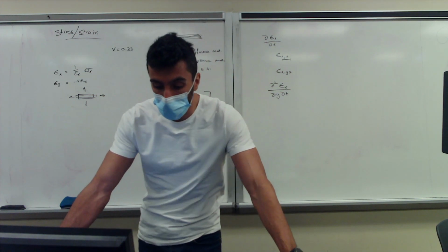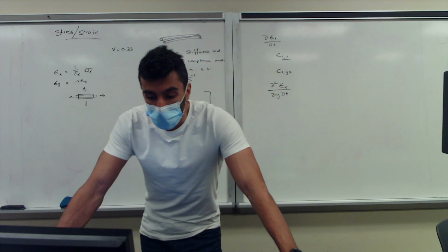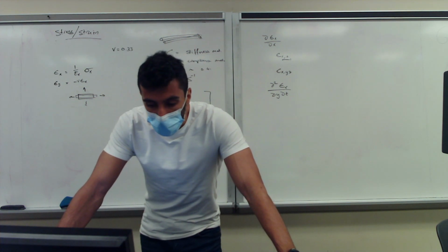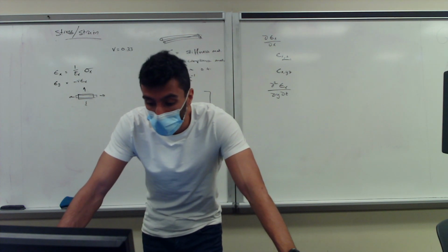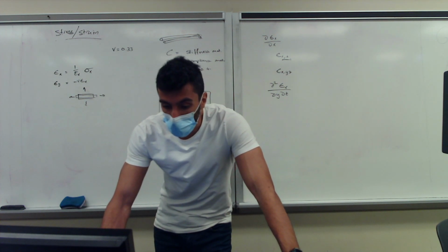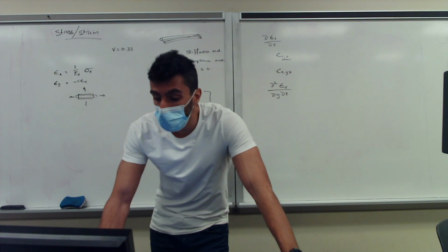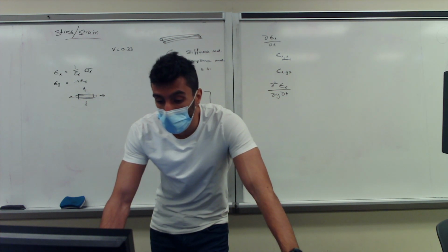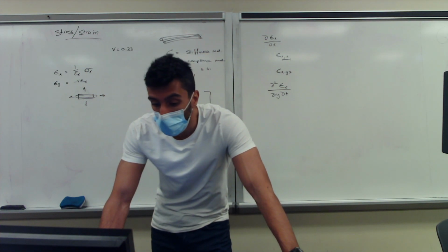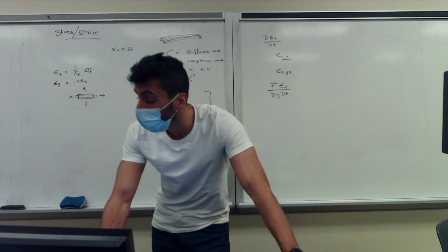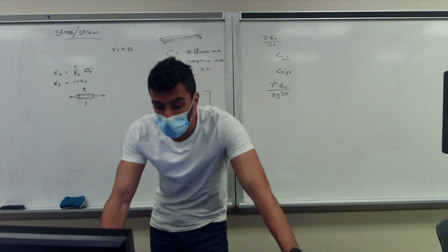He starts with the strain in xy. You differentiate with respect to x and y, and then you basically rewrite that to get your first set of 3 compatibility equations, and then the second set of 3 compatibility equations are taken by differentiating gamma xy and gamma xz with respect to x and z and y and x and y respectively, and you add those together.